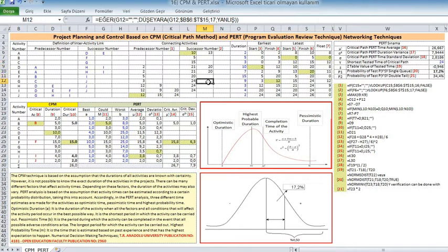Major steps of the critical path method. 1. Identifying the activities. 2. Construct the project network. 3. Perform time estimation using forward and backward pass. 4. Identify the critical path. The table given below contains the activity label, its respective duration in weeks, and its precedence. We will use the critical path method to find the critical path and activities of this project.